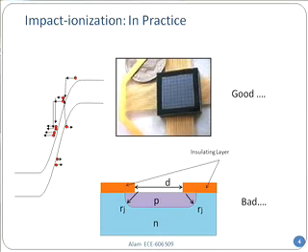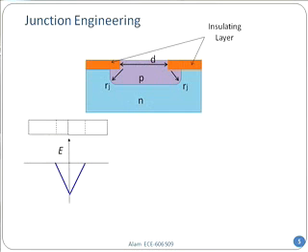That is because you haven't designed the junction properly. Junction electric field was too much. So when you're applying a reverse bias, this is breaking down from the corner, and avalanche is occurring from the corner. And then the diode cannot function. So depending on the application, different things might happen. How would you avoid that?